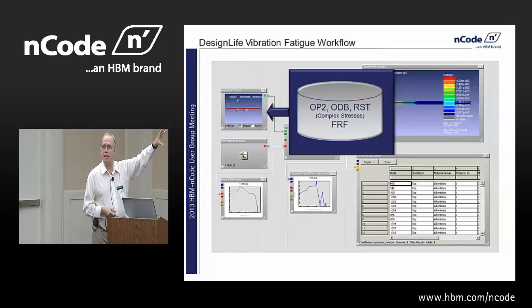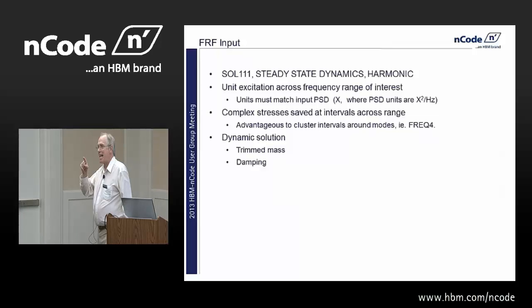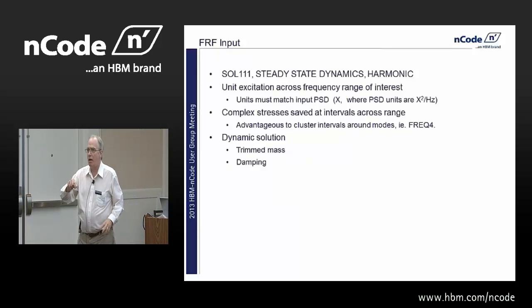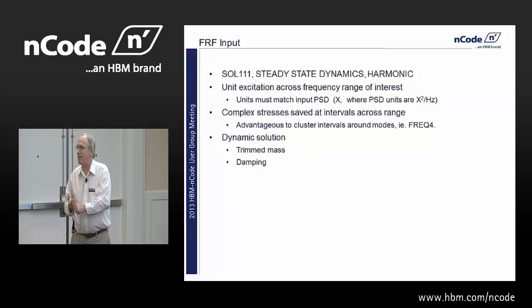What it really is, is a frequency sweep across a range of frequencies we're interested in, and we're saving out the complex stresses, the real and imaginary stresses, for those. That's relatively new to DesignLife, but the reason we do that is it gives us the ability to calculate principal stresses or directional stresses from these.